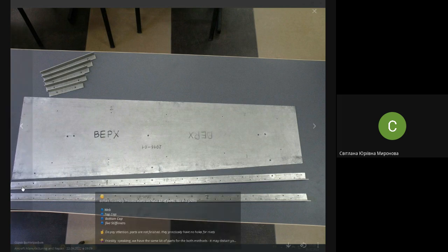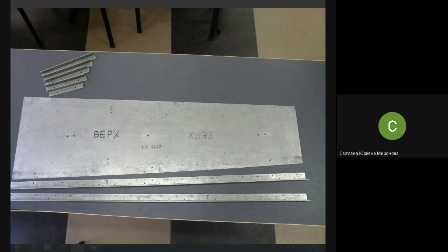And the same is done with these holes in the cap and in the web. Do assess this distance and you'll see that this distance and that distance are different, and even these two distances may be different, so that no one may rotate this cap into another position. No one may mix up the top cap and the bottom cap. The holes do not give such an opportunity to the employee. An employee in serial production shouldn't think. During pre-production, you are engineers thinking, and the employee works by hand. You are paid for your brains, they are paid for their skills, manual skills.